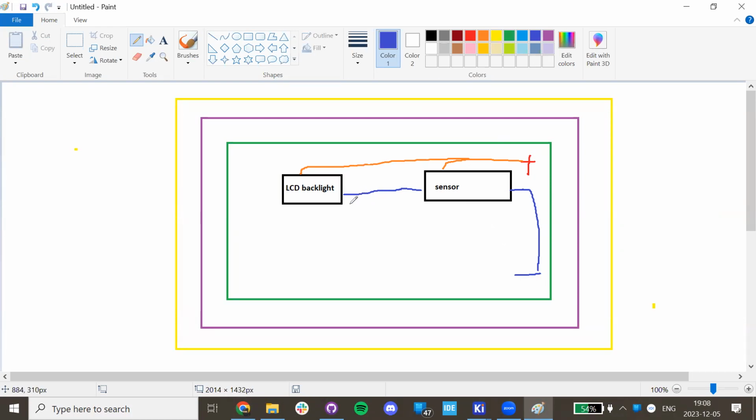impedance. So for there to be current going here down to the negative pole, you need a voltage drop, right? Because that's what Kirchhoff's law says. That applies for ground as well. So I'm going through this because it's not super intuitive if you don't think about it a lot, which all of you don't. Ground is not just a sinkhole for the negative parts or the receiving end of your battery, whatever you want to call it. V is equal to Ri applies here as well.